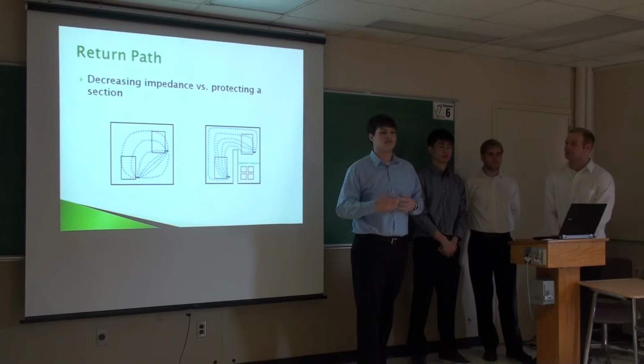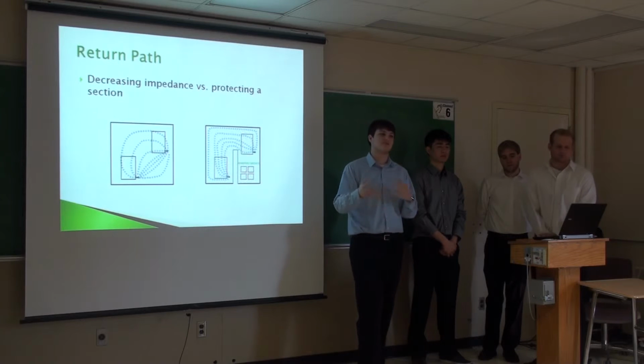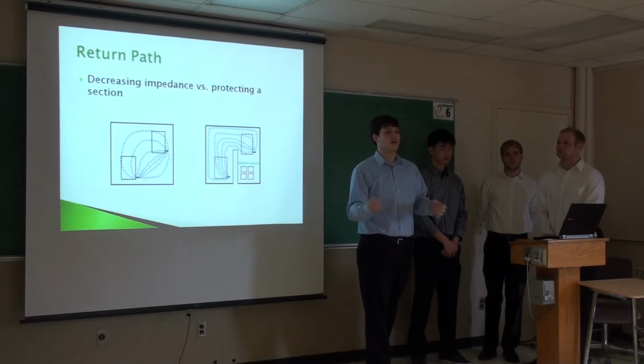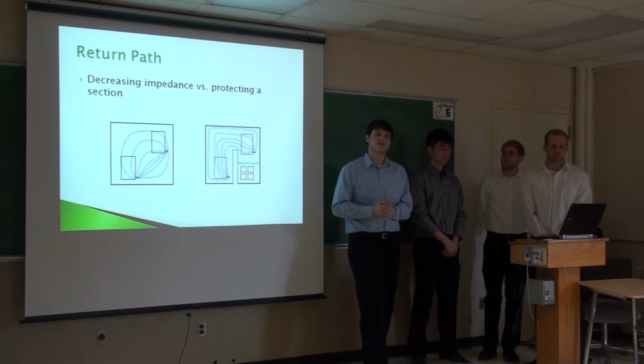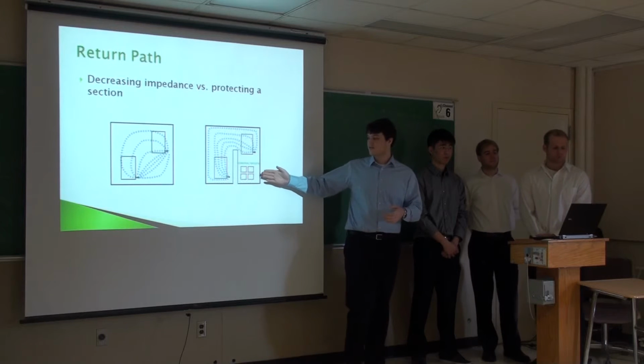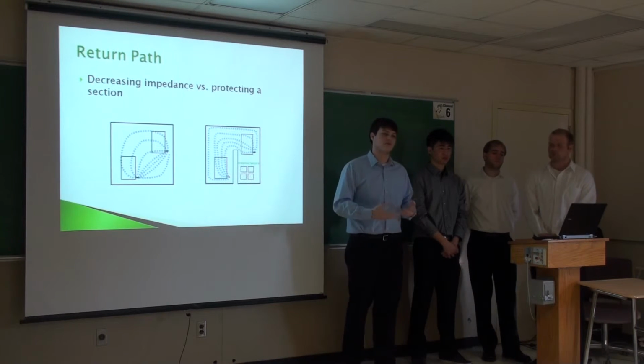As you can see, it's a very direct path, and it spreads out to find the path of least resistance, to find the lowest impedance possible between the two chips. So that's one option, to make it just a solid plane and have very low impedance. Part of the problem is that the current, as you can see, takes up the entire ground plane. So if you have some section of sensitive components, there'll be a lot of noise underneath on the ground plane.